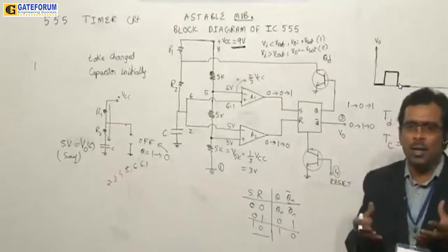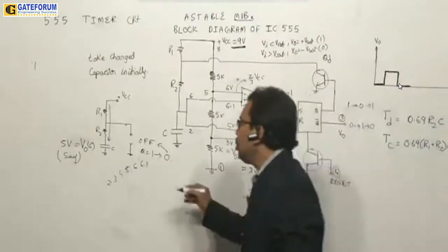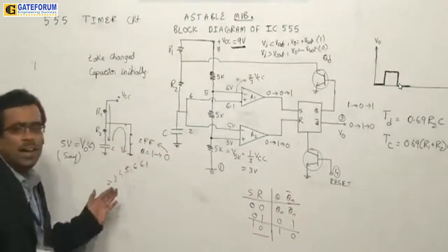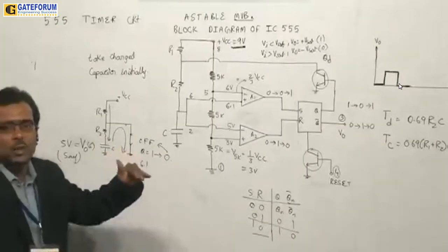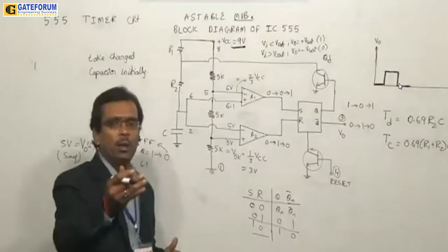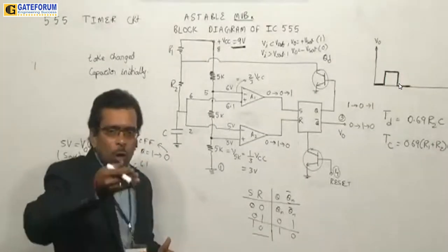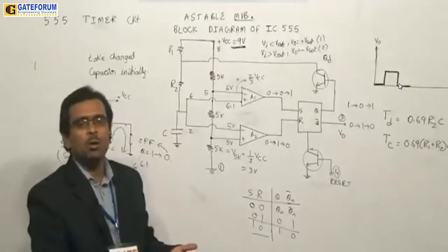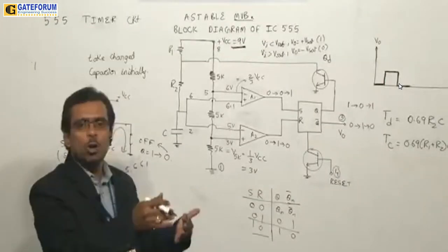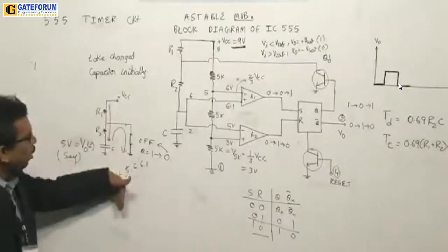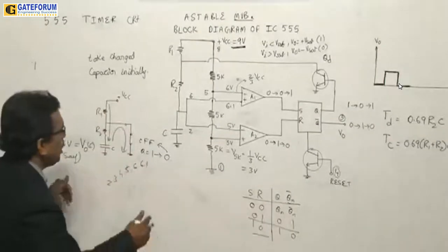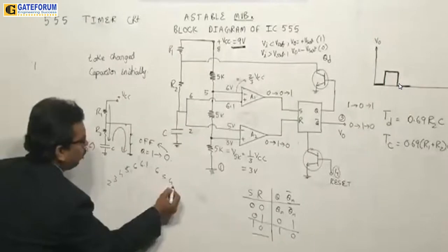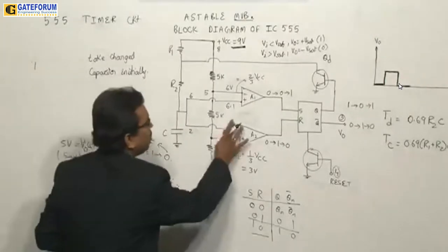Once the transistor is on, now the capacitor cannot charge further. It has to discharge. So you can observe here again the capacitor is going to discharge. Just now the capacitor has charged up to 6.1. So it wants to charge more, but it will not get the opportunity because the transistor is acting as a short circuit and it will return back towards low voltage now. So again the capacitor voltage falls down. Everybody carefully observe this. It falls down to 6, 5, 4, 3, 2.